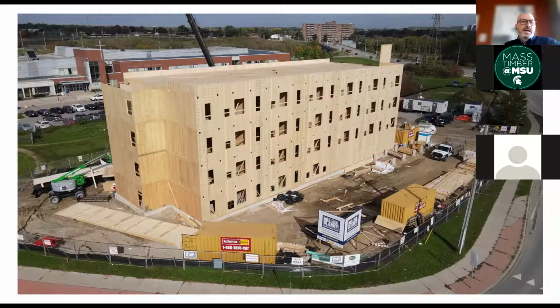Those are single panels that are 4 stories tall. So the panels in this case will be either 8 or 10 feet wide. They're vertical panels. The vertical panels are the full length of the building. And when we were erecting this building, I believe those non-structural panels went on the building in about 10 days. That whole structure that you see there was assembled in only 20 working days. So if that gives you any indication as to how quickly the superstructure goes up, you can see that there's significant time savings there. Next slide, please.